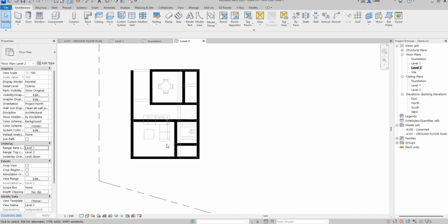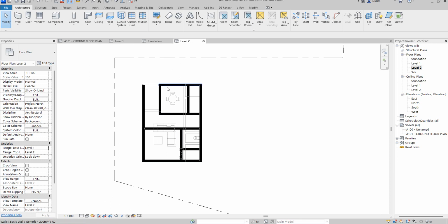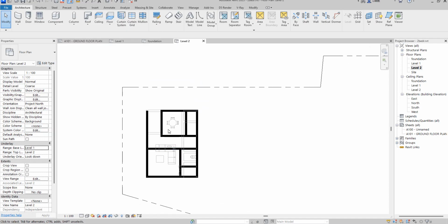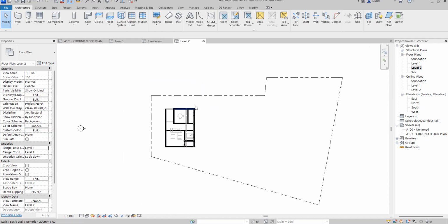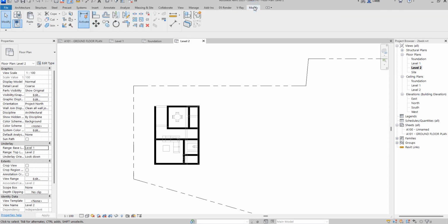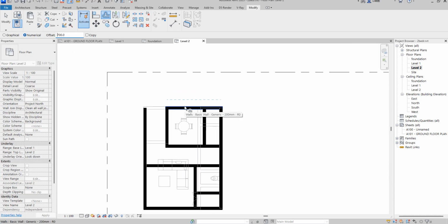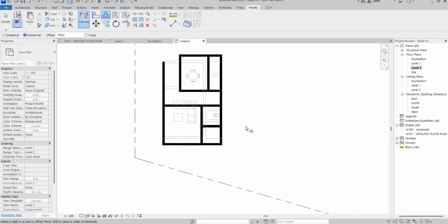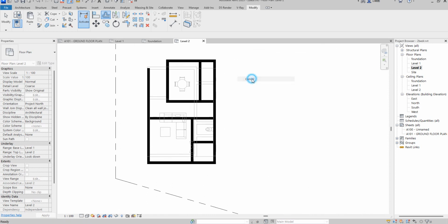So this is it. Now, as I have done, this needs to be cantilevered. You can't just leave this particular building this way, because the ground floor is limited in space, but the upper one you can extend as much as possible. So I'm going to increase the cantilever of this one by doing offset. Click on offset and say offset without copy. This time around, instead of 6,000, what I'm going to use is an offset of 700. So I will do it that way. Then do this one. So that is the 700 offset.